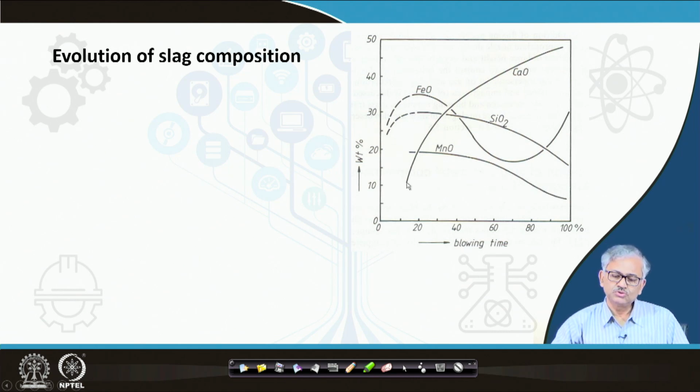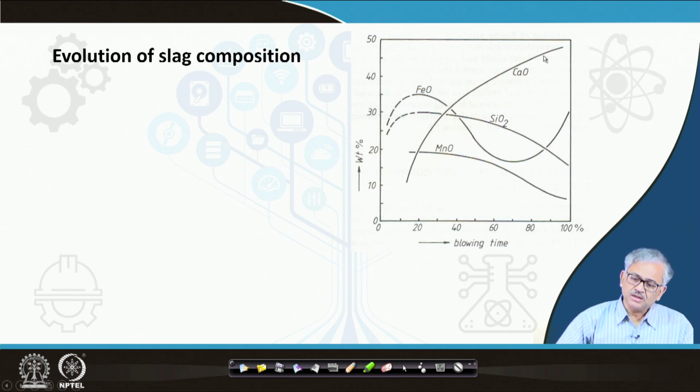You can find that the CaO appears here. So, CaO in the slag starts dissolving and it appears in the slag, and finally you can see that the CaO percentage increases in the slag, like this. It is increasing, and rapidly it is increasing after some time, when the basic slag forms, that is, after some time the CaO starts dissolving and it increases.